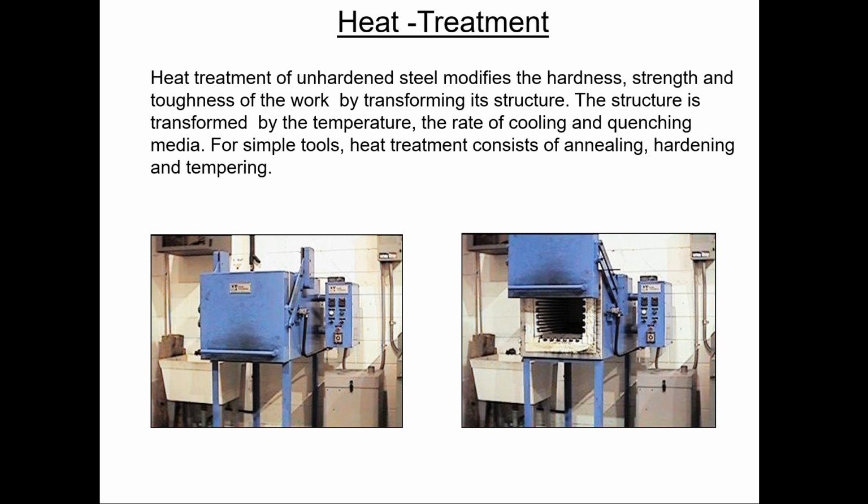So I've had a lot of tools that sit in about 400 or 500 degrees for a long time. It hasn't seemed to affect the strength or the operation of the tool, the clamp, or whatever I've happened to use for a long time. But that's a really good temperature for welding materials, as you'll find, that's already hardened. If the material's already hardened, you can actually weld it and leave it in its hardened state. We don't have to wipe out its properties. You're going to do a good enough job at that, welding it. But we do have to preheat to get rid of the thermal shock capability.